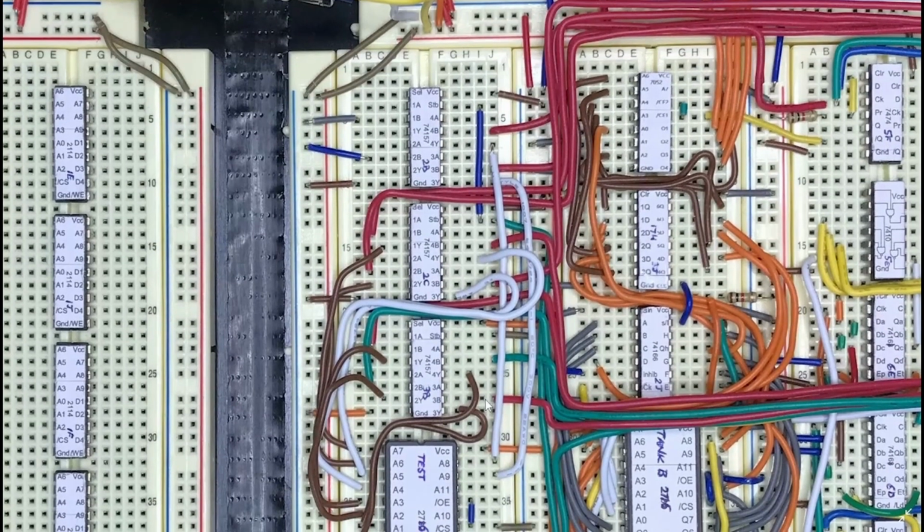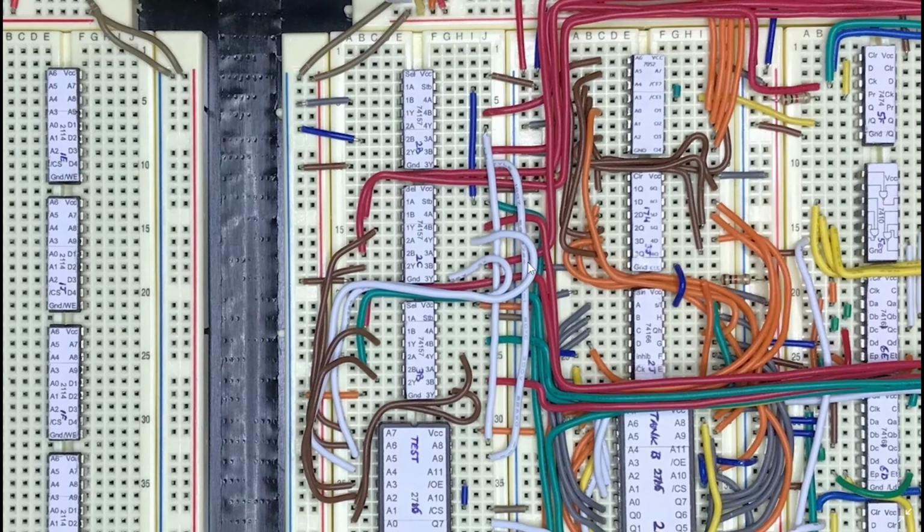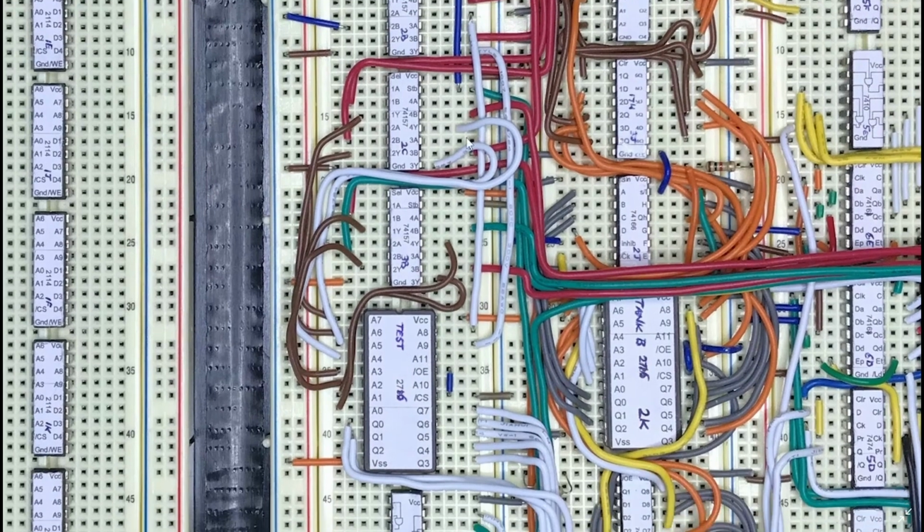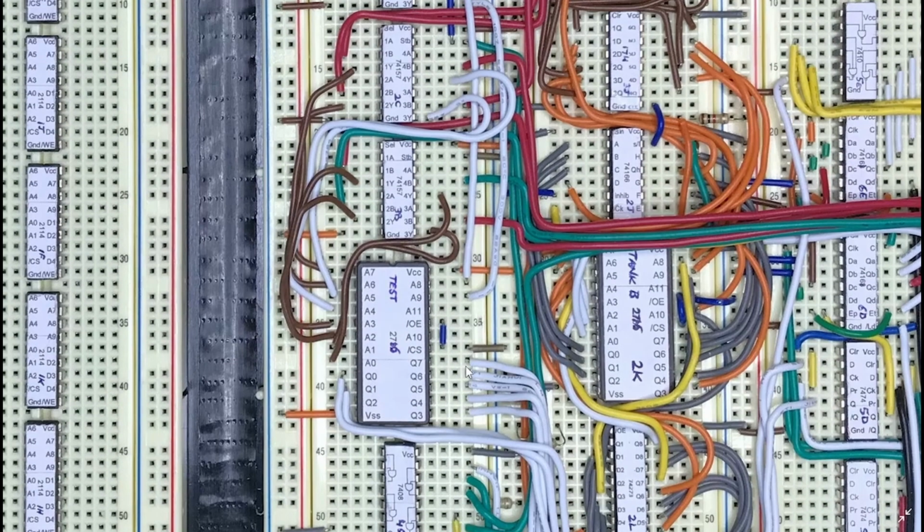And then, as we said before, we've got these selector chips here, the 157s, that are connected to the 161 timers that are creating the kind of lookup table. So it's doing a search from 0 to 3FF, and then that is creating an address lookup to look up in this ROM chip.